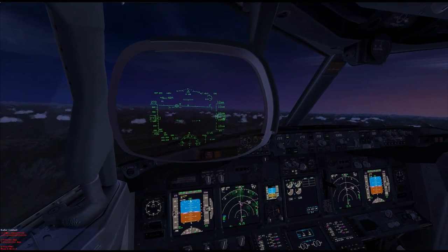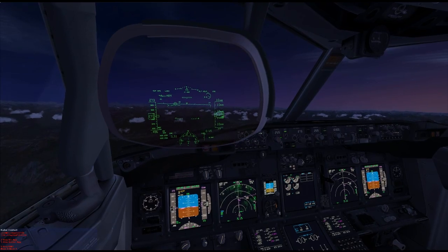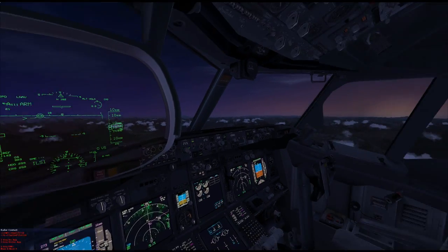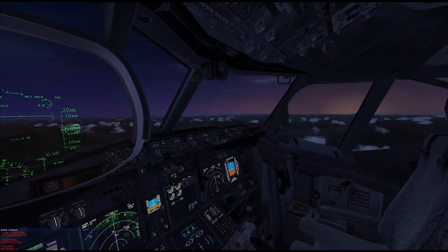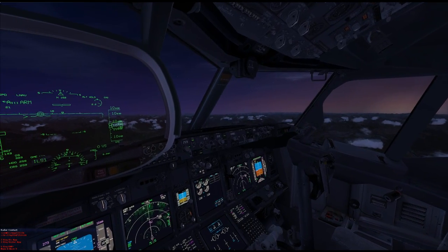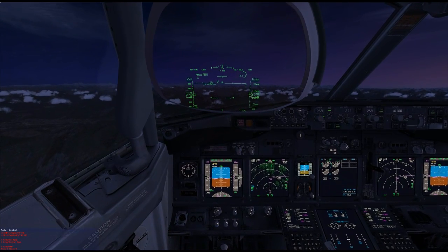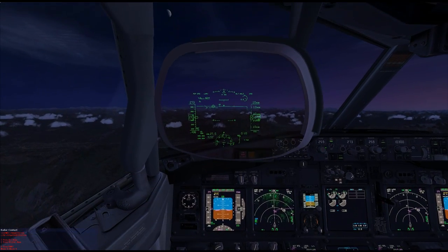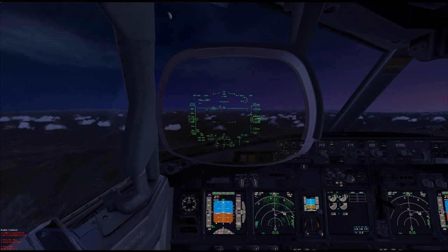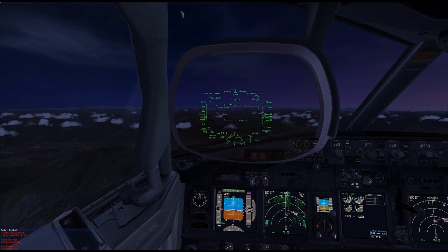Pressurization. Landing altitude 1850 feet. Checked. Auto brake, level 3. Landing data, Oscar Echo Papa Juliet Papa, contact tower 120.3, minimums 200 feet. Approach briefing completed. Descent checklist complete.